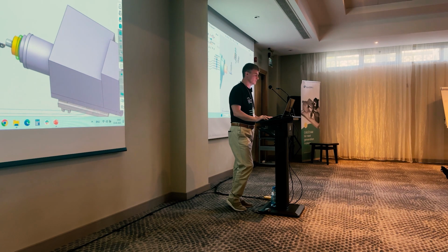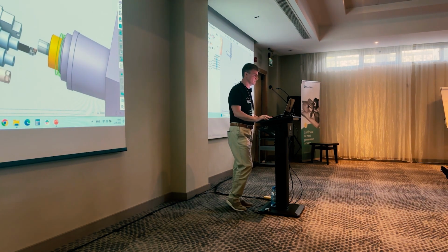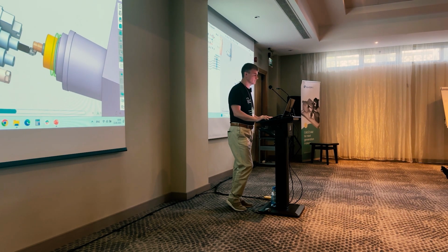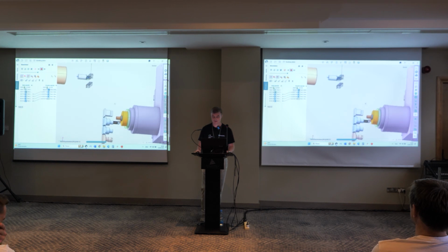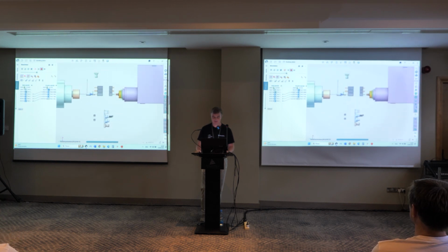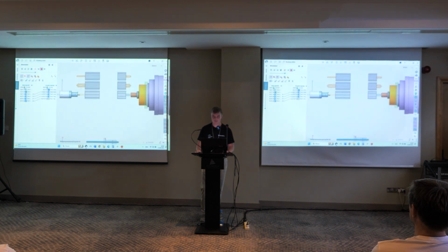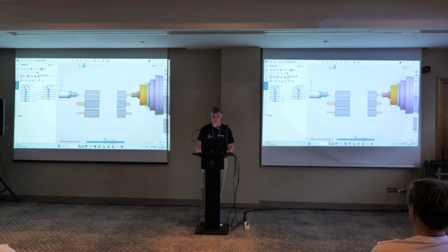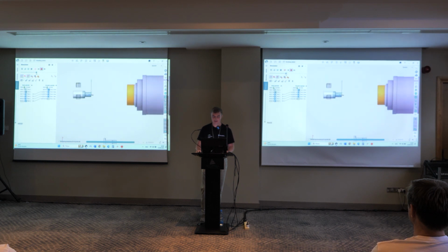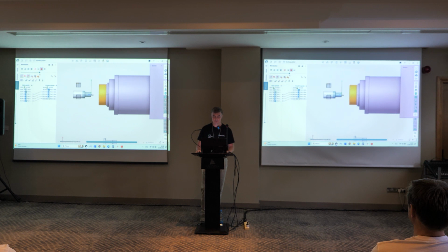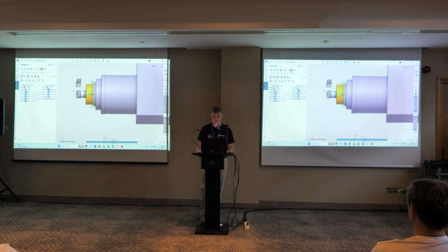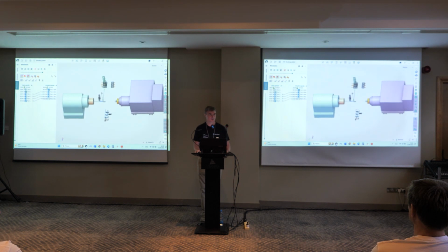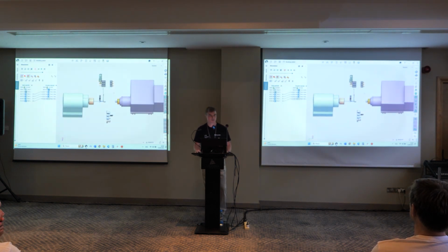I run simulation, so it machines two parts together, the parts in the main spindle and the parts in the subspindle working together. After that, we machine with these tools synchronized drilling of two parts. Next machining, next drilling. After that, go away and take over. The subspindle takes the part, the tool cuts off and removes. So it's a little bit of simulation of a Swiss lathe.